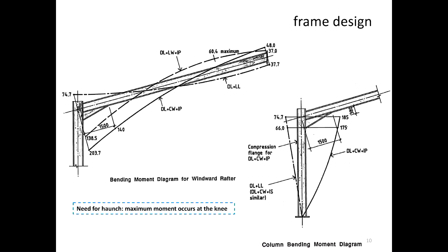So if you're on site as a project manager and you have this engineer who has gone out on a Friday night, came home on a Saturday morning, does the design at 12 p.m. on Saturday and sends you the design with the bolted splice where the moment is maximum, send that back to the engineer and say that is wrong. That is the reason why you need to understand some of these things, because it happens. Not deliberately. Probably it can be a drafting error where it's been wrongly placed.